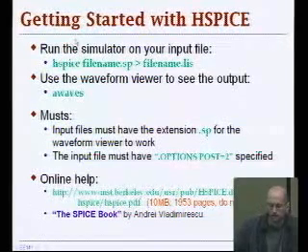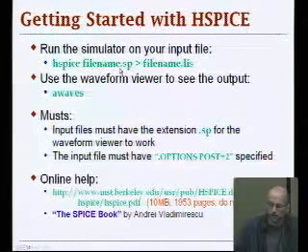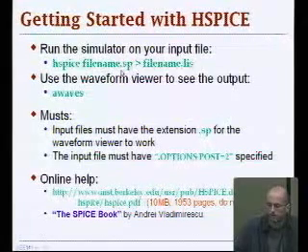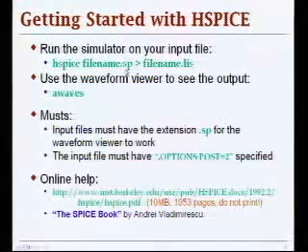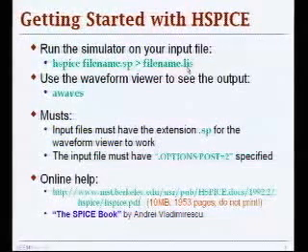So once you get instructional accounts and are able to log in, you have to run the simulator, and to do so, you have to have your SPICE netlist that has some name .sp. It's very important that you have, it's basically a text file with the extension sp that the tool understands. And you can direct your output into a log file, in this case, with the extension lis.